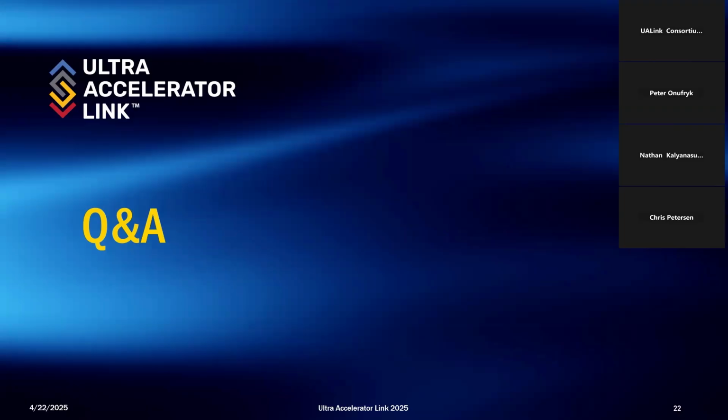Excellent. Thank you, Peter. The next question is, how is UALink different from PCI Express technology? So I could comment on this one, Nolan. The first critical difference to notice is that UALink is specifically built for scale up. And it is also built in such a way that it allows flexibility on the physical layer. Since we've been talking a lot about the Ethernet physical layer, the first notable difference here is that Ethernet 200 gig is widely available at this point. And so you get a significant increase in bandwidth as a side effect of being able to run on top of that Ethernet physical layer.